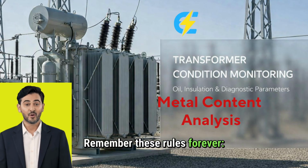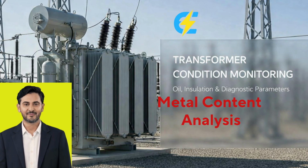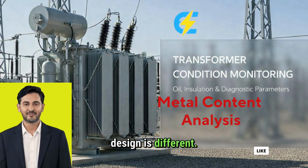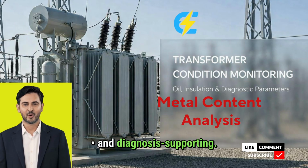Remember these rules forever. Metals should be near zero in healthy oil. Sudden increase is more important than absolute value. Metal pattern matters more than single metal value. There are no universal alarm limits in standards, because every transformer design is different. That's why metal analysis is condition-driven, trend-based, and diagnosis-supporting.